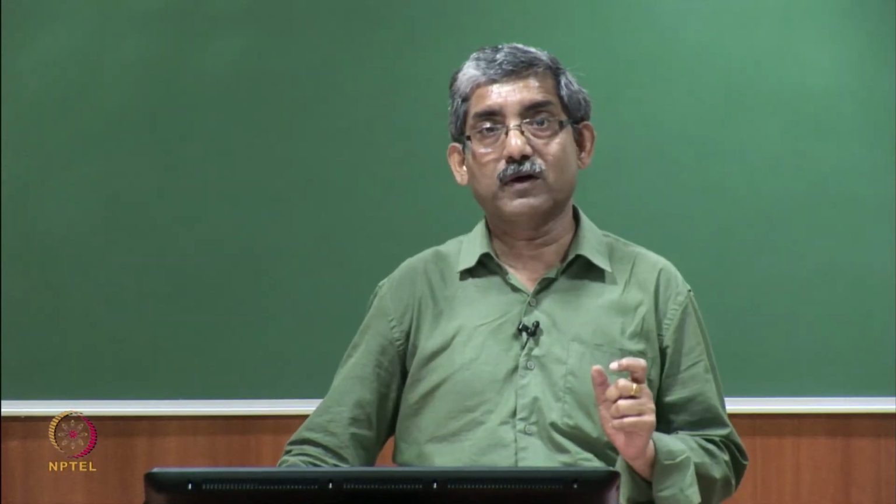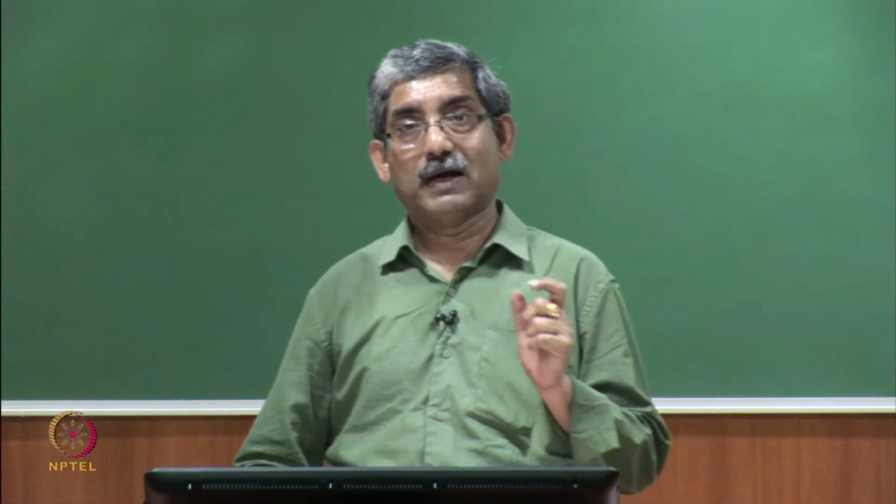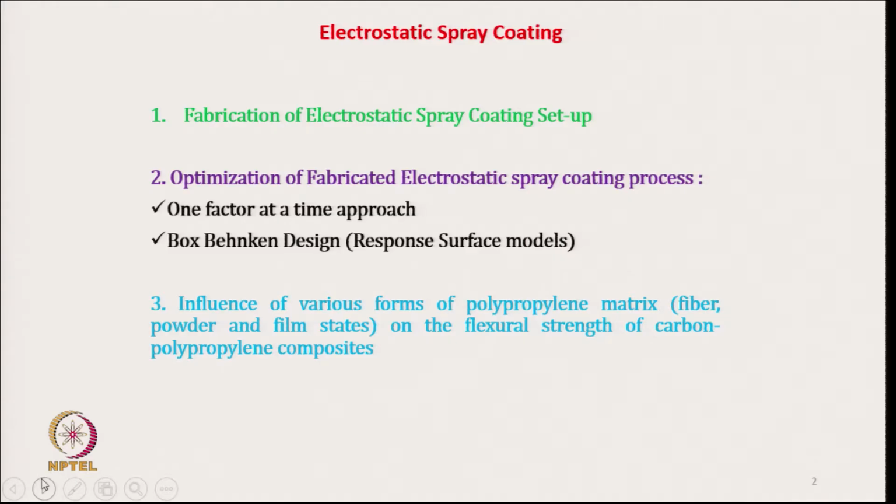So, forms of matrix are fiber form, powder form and film form. We used the polypropylene in these forms and we have studied mainly flexural properties.